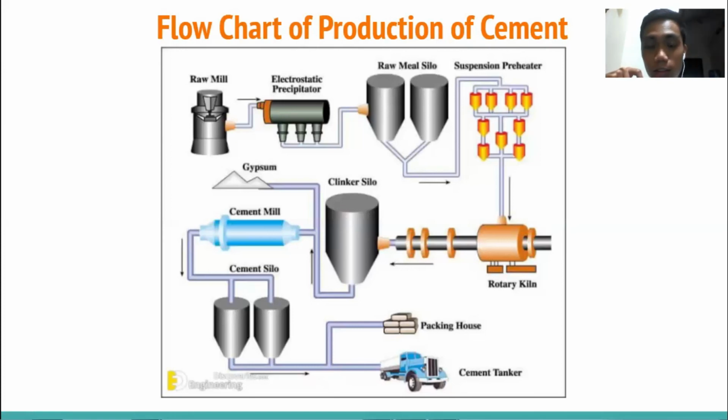So, quick rundown on the main differences of wet process and dry process. So basically, wet process needs a bigger kiln as it accommodates a slurry, resulting to a higher fuel consumption than dry process. Wet process can easily be mixed as its material has water, so a better homogeneous material can be obtained compared to the dry mixing of dry process.